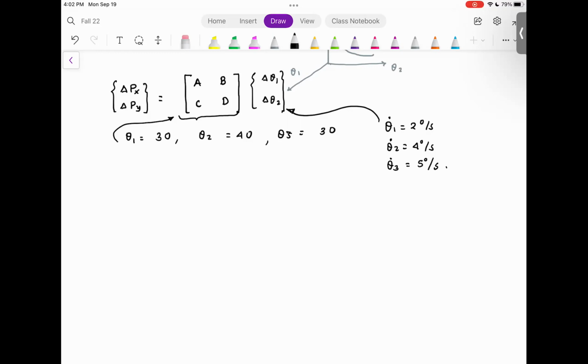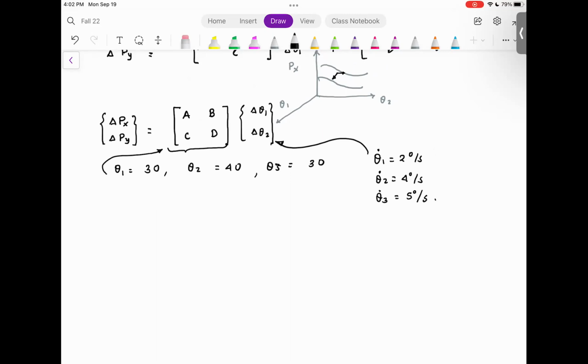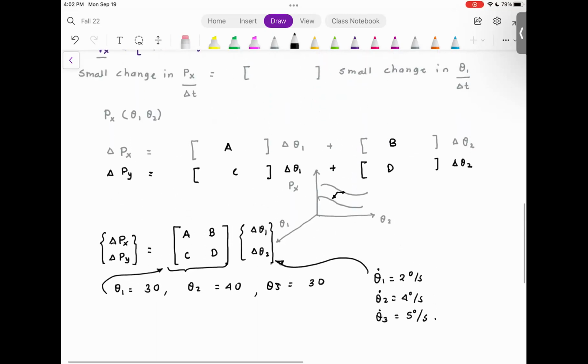Usually, what errors can affect the joint velocities and the proportionality with the end effector? So this is all good. What we talked about is all great in theory. In actual practical examples, you have an encoder attached to the motor. You have some type of sensor monitoring the workpiece. And the data coming from the sensor and the data coming from the encoder could be at different update rates.